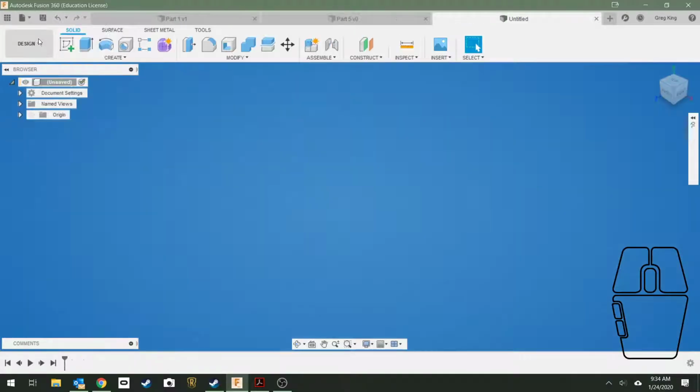Next part, we're looking at number 7. We're going to use a loft. You can only do this part with a loft. Only way to complete this part. Number 7, there's really 2 ways to do it. You can create the 2 shapes, the front and back shape, as a whole, and loft between them. With 1 move, you're done.